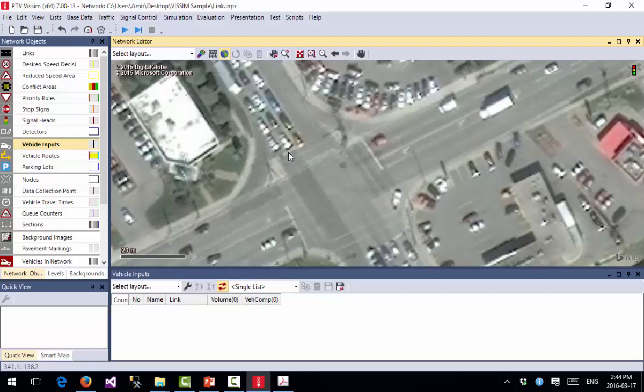If this information is available, you can put it into your simulation and define your OD matrix, or you can define a dynamic assignment here. But normally, in normal traffic studies, this information is very expensive. Normally, it's not available, and it's very hard to obtain. Normally, what people have is the turning ratios. They put some counters, or they have loop detectors. They have the count of the vehicles here. So, for example, they know that from this direction, the flow is 2,000 vehicles per hour. They don't have any information about demand.